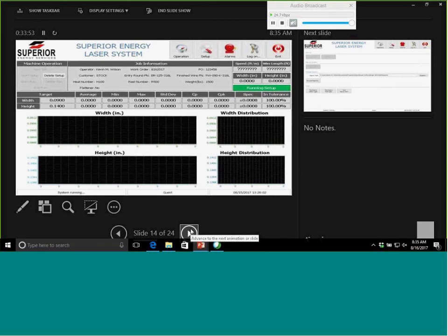And then in the upper right hand corner we indicate line speed of the machine, and then we also show the width and height, which is supposed to be the default settings. And then down below that we have graphics that illustrate where we're at, and it will detect as we're moving if we're into a pass mode or a failure mode. And if we do get into a failure mode, we sound off an alarm, and it will indicate at what footage we were out of spec. So it's a great tool.